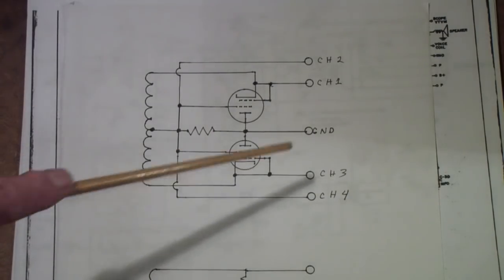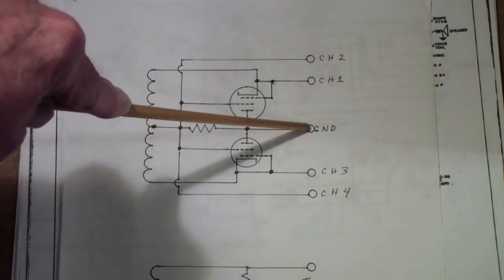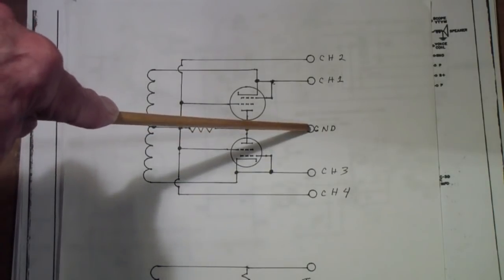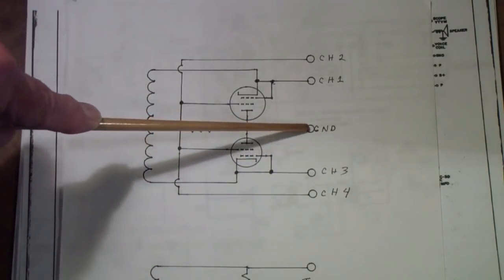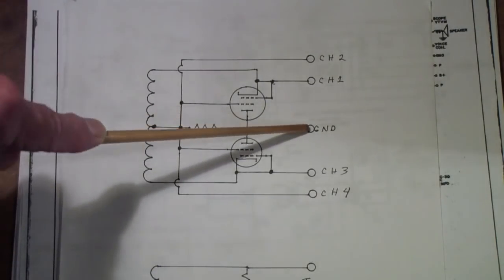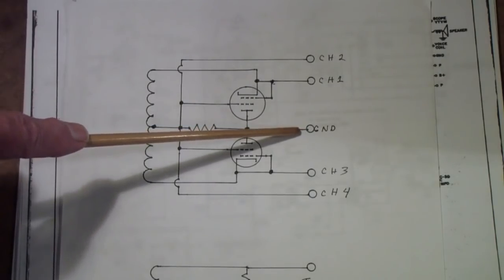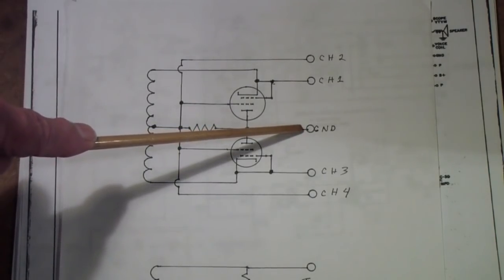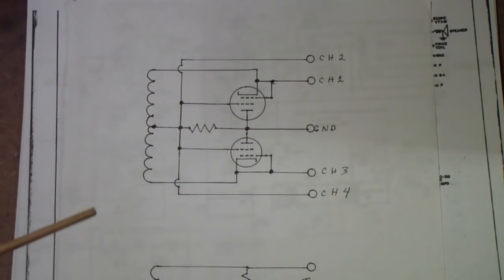And so if you hook anything to the ground of the oscilloscope other than a floating signal, you can short out your AC power. And one of three things will happen. Either you will blow up your oscilloscope, or you will kick the circuit breaker, or worse. And by worse, I mean you can have a fire, you can be electrocuted, a lot of bad things.